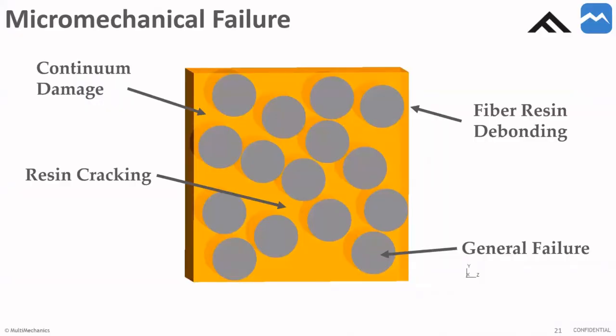So I guess a question for both of us is about a little more detail on measuring the fiber matrix interfacial strength. Computationally, what you input is either just a straight-up strength for the cracking to initiate, or you can also have an interphase region, so you have one element, and then you can represent that element through a material model, like continuum damage, to represent that failure differently. But it's a good question. How do you actually get this?